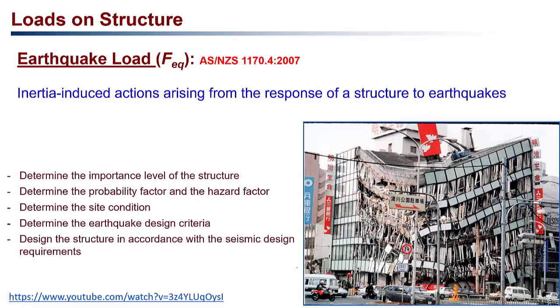And then you also need to know the site conditions. What is the site condition of where you are constructing the building? That will give you the earthquake design criteria, and based on that earthquake design criteria, you will do the seismic design of the structure.